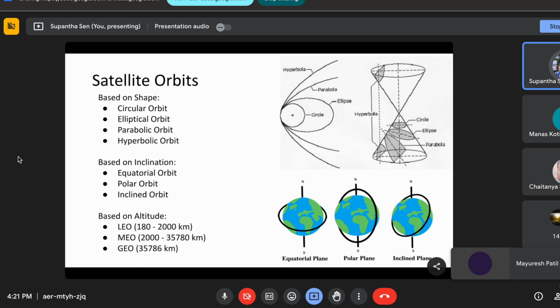Mostly we put remote sensing satellites in LEO orbit. There are some constraints why we put them in LEO, not in GEO. NASA, ISRO and some other global space organizations have tried, but from GEO you will not get the resolution of the image that you get from LEO. So we put remote sensing satellites in LEO at around 600-700 kilometer height. That depends on the application again.